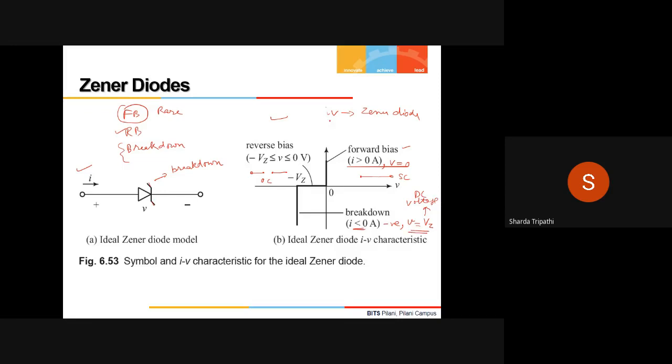That's the only difference. We have already seen this, but now we need to see it with the help of examples. If the diode is in the breakdown region, I simply substitute it with a DC voltage whose value is given by the breakdown voltage of that diode.